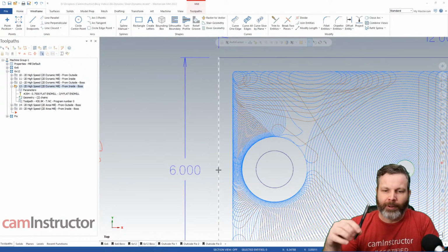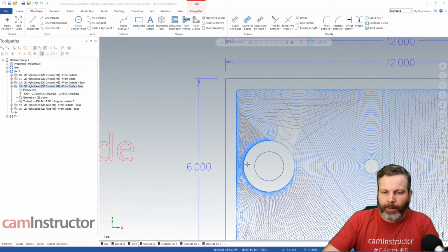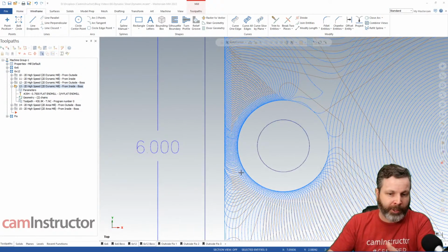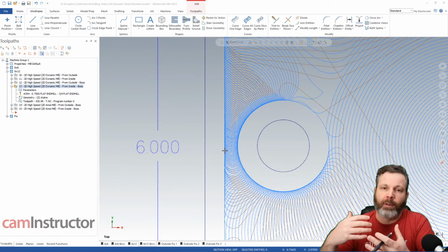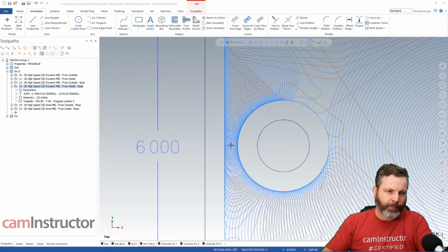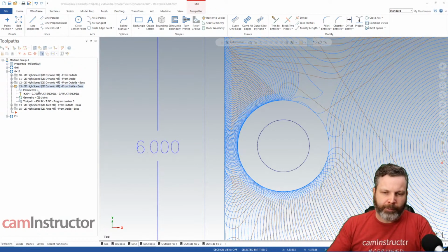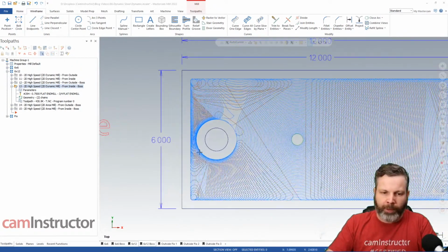if our cutter at 100 inches per minute is right on the border of breaking, and the equivalent to 100 inches per minute inside this section of the toolpath is 30 inches per minute, and we're feeding at 3 times that, we can have a problem. Okay, so how do we go about addressing that? So there's no feed rate override inside Dynamic, so there's no switch that we can turn on to fix that, but we'll have to address it.